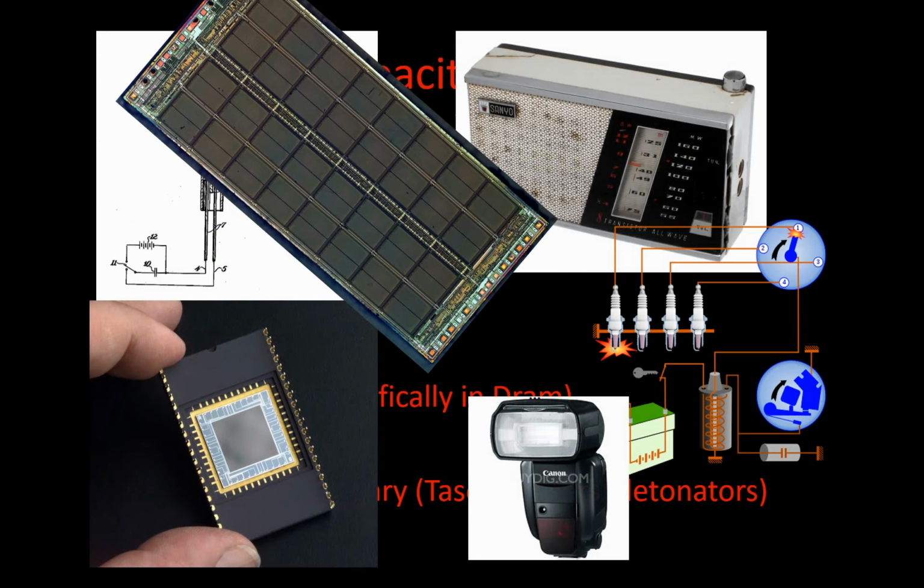A camera flash is my typical example. This is actually an RC circuit that we'll discuss. If people remember having a camera flash, you would switch it on and it would make this sound as it charged. So you could actually hear the capacitor charge and the charge build up on it. And then as the pitch built, it eventually slowed down and stopped as the electricity charged that capacitor and left the charge on it to be released in one flash. So if you press the button on this flash, it will release all the energy in one burst.